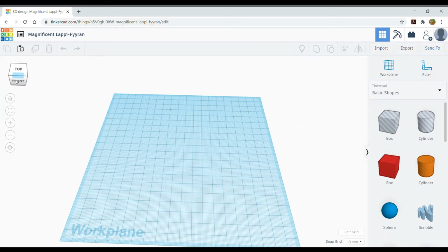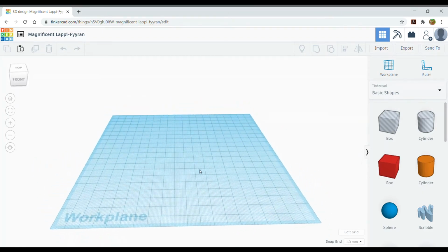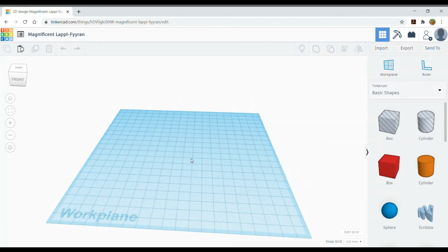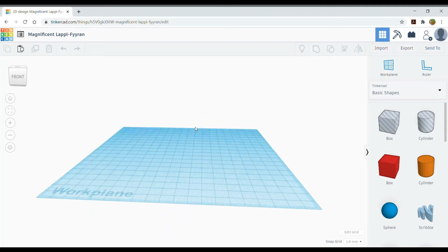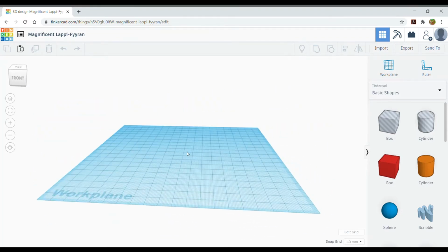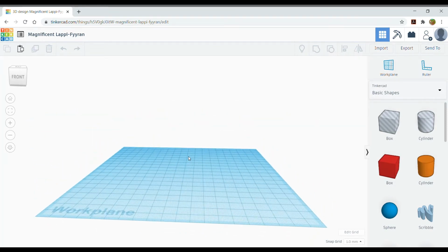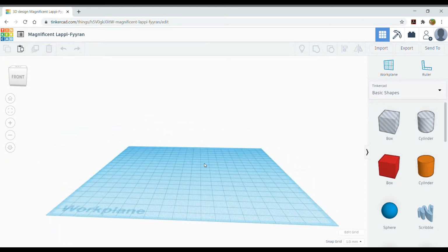Okay, and if I want to actually move the pan around the plane, I can click the shift button. Sorry, not shift button. If I use the right mouse, I can do the rotation. And if I use the shift plus the right mouse button, I can then pan the thing around.